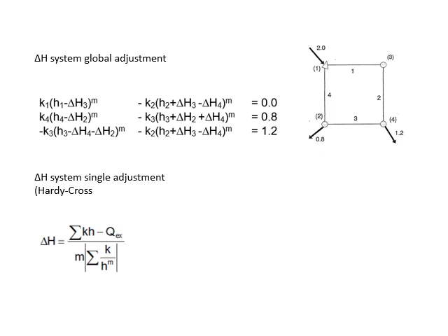Here we have three continuity equations in terms of delta H for three different variables: delta H2, delta H3, and delta H4. And we use the correction if we want to correct for single nodes. We use the delta H equation in the last line, but if we like to have a solution for the whole system by solving a system of nonlinear equations, we choose the three equations at the beginning of the slide.